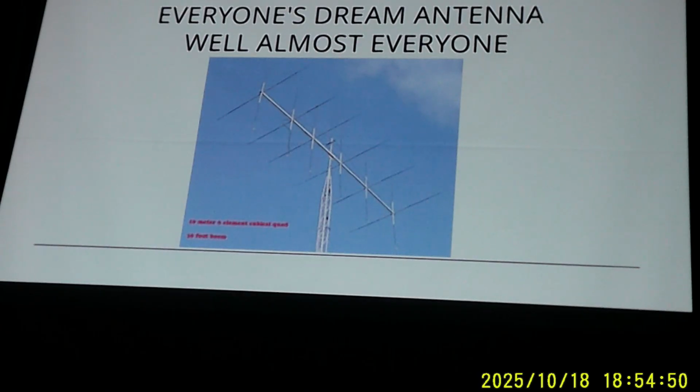If you're on our 10-meter net, well, you want vertically polarized, because almost all of us are using vertical antennas. If you have a wire antenna and it's horizontally polarized, will it work? Yeah, not so well, but we may still hear you, and you may still be able to hear us. But I'll guarantee you, you put a vertical up in exactly the same spot as your horizontal, you're going to do better, because we're doing the same thing, this way rather than this way.